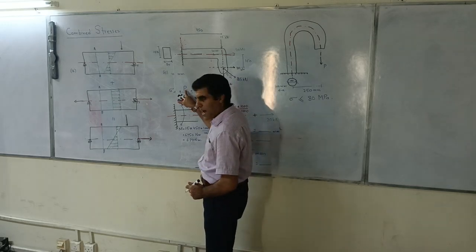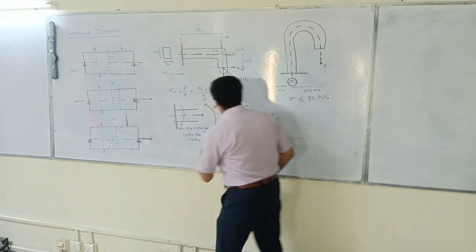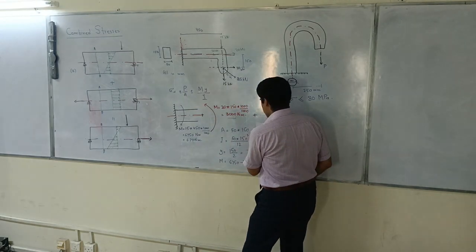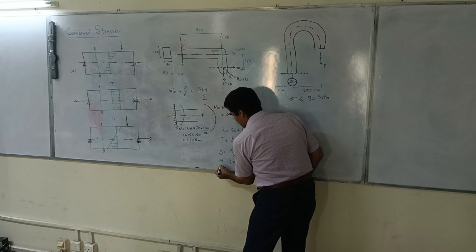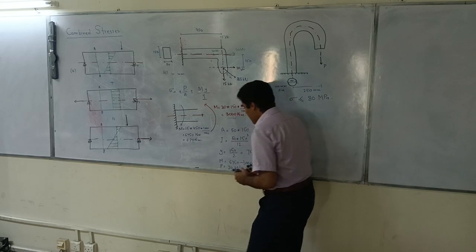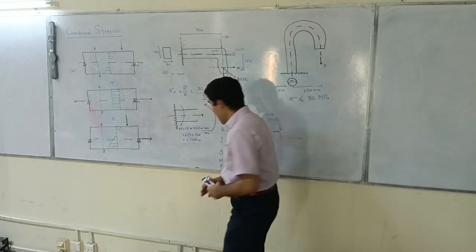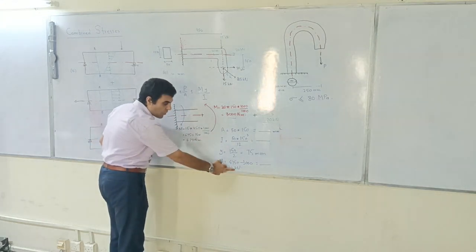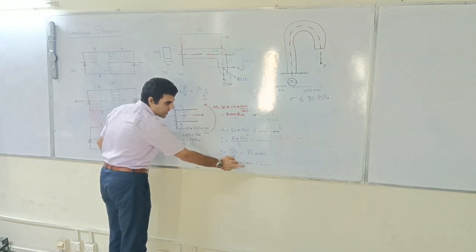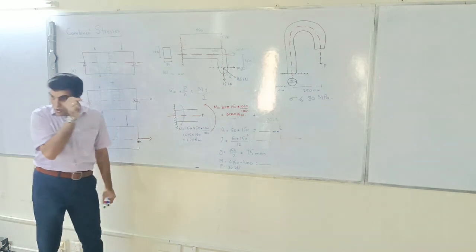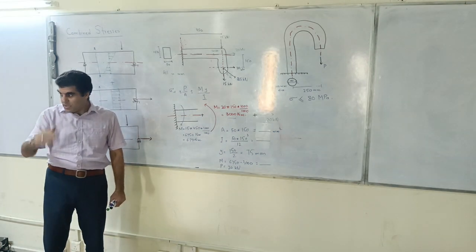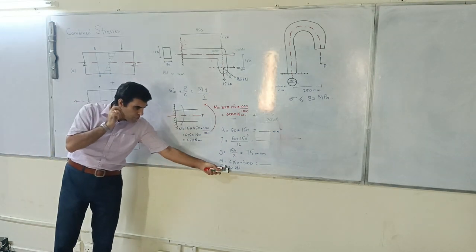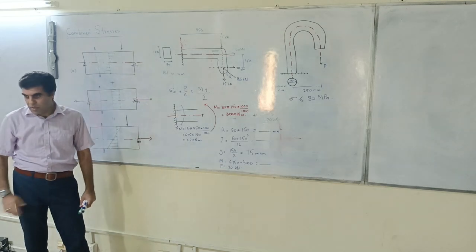And we have applied load P, and that P is 20 kilonewton. Now, please notice that if you put in this equation P as in kilonewton, you have to convert this also into kilonewton. It should be like with the like. Or either you should use 20,000.